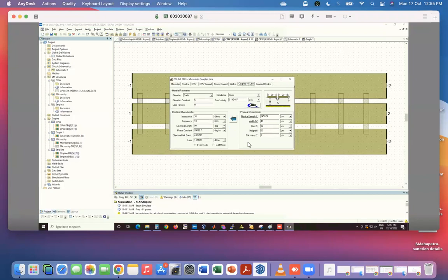If I forget this ground plane, then that looks like a slot line mode. So what is that slot line mode in this picture? It's the odd mode. Because remember, the even mode goes like this, both the plates together, and the odd mode goes like this. So the odd mode is sort of like a slot line mode, and it's more controllable and easy to connect to in terms of external interfacing.